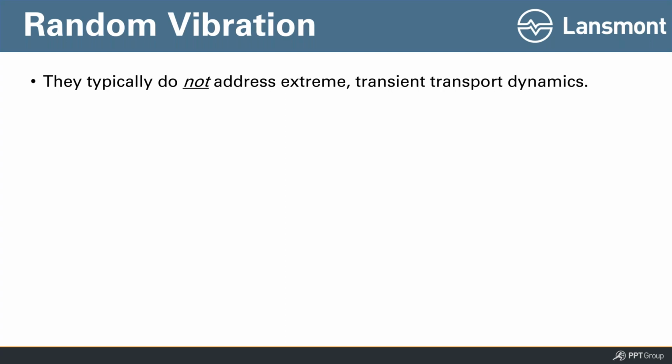There's been a lot of talk about it. There's been talk, I would say, over the last 20 plus years of how to account for some of that, but it's really separate. And the answer is, well, there isn't an answer yet. Some of the things we talk about are shock on vibration or transient on vibration testing. Is it a standalone extreme input that addresses things like those bridge crossings, rail crossings, potholes? But we don't typically blend them into a random vibration test.